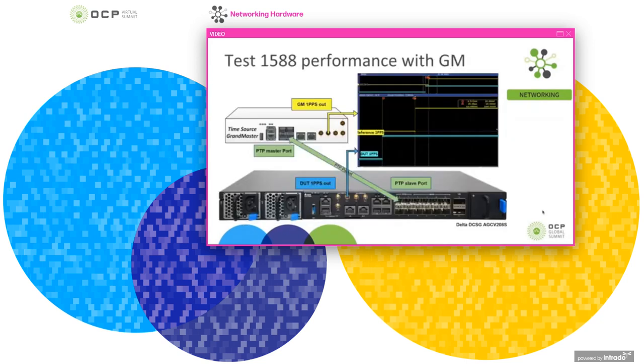So how do we test 1588 performance? We use a grandmaster. The grandmaster will be a timing source here, so we use an Ethernet connection with our DUT. Here, we use the Delta cell-site gateway router, AGCV208S, as an example. You can see the green line in the middle. That is a PTP packet transmitted in the 1G or 10G interfaces, transmitting 1588 packets in order to achieve